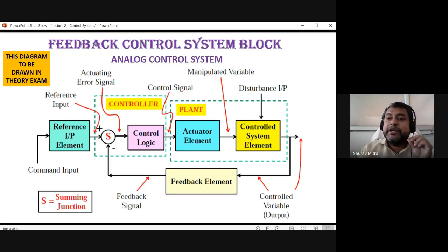Likewise, this is called the control loop, and this is called control lag: when the error happened and when it again comes back to 70 degrees. This difference of time is called control lag. And control lag does not contain one loop. After 3, 4, 5 iterative loops, because from 50 degrees the temperature will not come directly to 70 degrees, the process is a slow process.